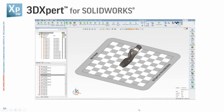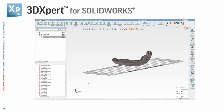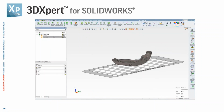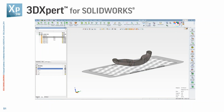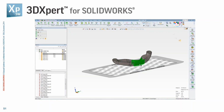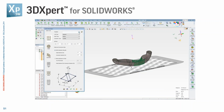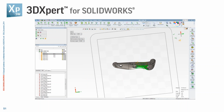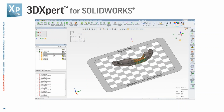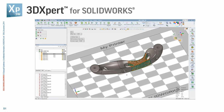Some other things we can do, just to have a look at this part, is divide it into different sections. And we want to do this lattice in different areas of the part. So basically we're cutting the part in different zones, and we're going to end up with some settings on this zone with these lattice parameters. So this is the internal mesh we can do to make things lighter or modify the internal structure of the 3D printed part. So we don't need to fill it up as a solid. It will take a longer time and maybe not be necessary for this prototype or this application.